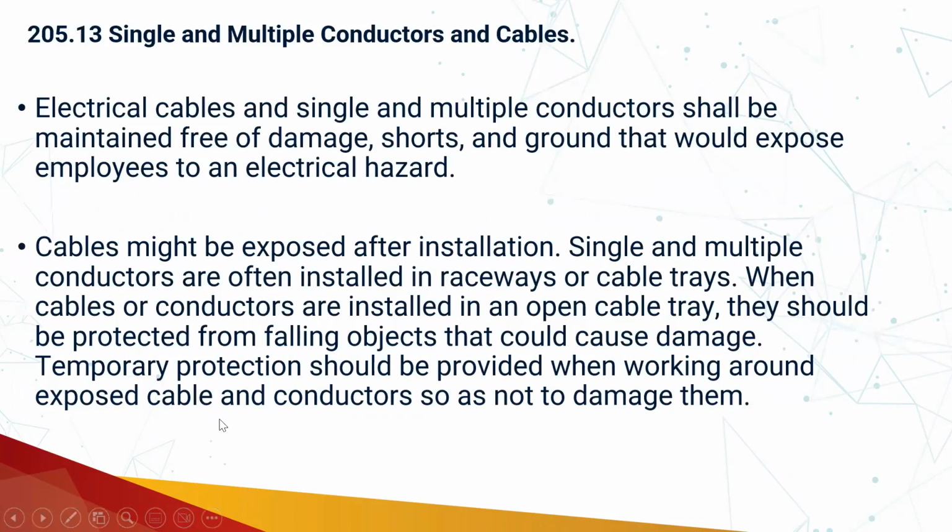205.13, single and multiple conductors and cables. The electrical cables, single and multi-conductor, shall be maintained free of damage, shorts and grounds that would expose employees to an electrical hazard. So the cables need to be maintained in such a way that there is no crossing of those cables, and there is no heating of those cables due to close proximity, which is derating the cable itself and causing some aging effect on those assets, which can cause issues like damage, shorts and grounds.